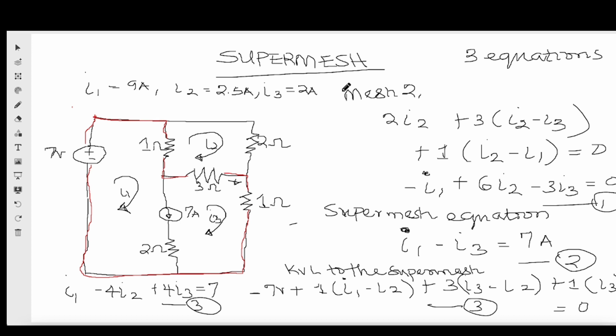If the same circuit has m distinct meshes, then we will obtain at most m KVL equations. Each supermesh will reduce this number by 1, and based on this fact, we should select the approach that will result in a smaller number of simultaneous equations. The more the simultaneous equations, the more difficult it is for you to solve. The highest I've seen in a normal scientific calculator that can be allowed in an exam hall to solve is 4 simultaneous equations.